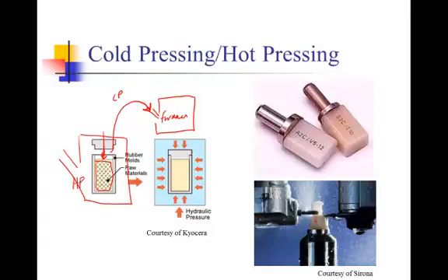So it is sintered and pressed simultaneously, and that requires a very expensive type of furnace, so it's rarely used. Now we have two methods of accomplishing the pressing. One is called uniaxial pressing, where we just apply pressure from one side and make the plunger a little bit deeper so that it packs the powder into the shape that we want it to have.